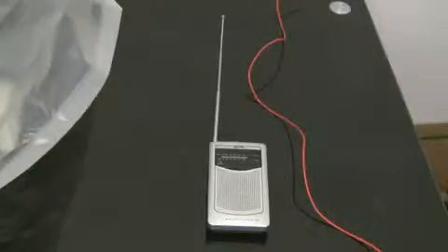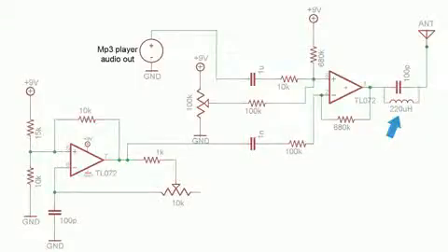This is a very low-powered, unoptimized design, so don't worry about any legal issues. It's only going to have a range of a couple of centimeters. If you want a little bit more range, add a 220 microhenry inductor in parallel with a 100 picofarad capacitor over here. What this will do is cause the current in the antenna to resonate, which will result in more energy being turned into radio waves. I'll do a video on LC filters and resonance in the future.